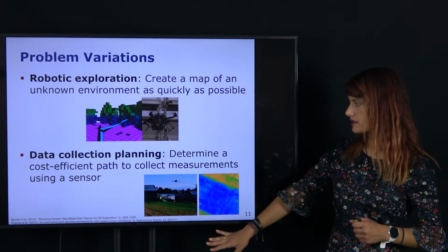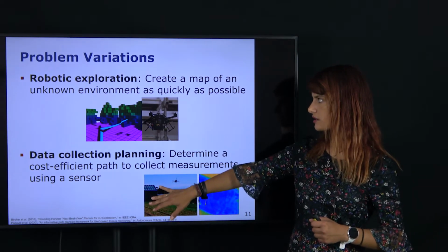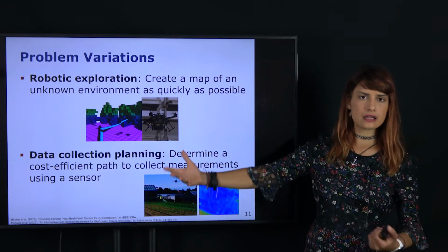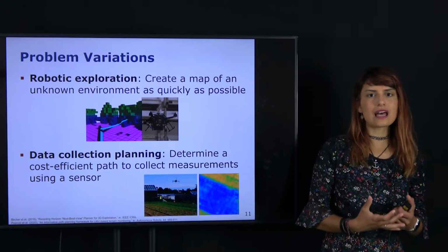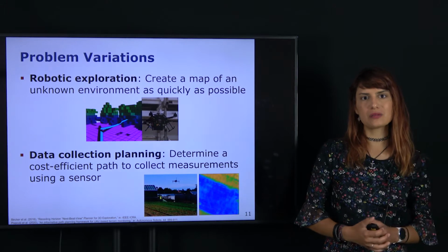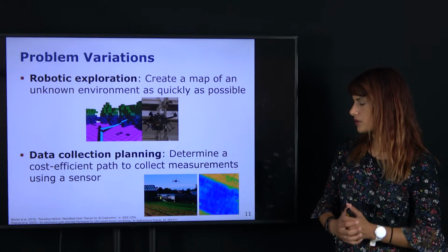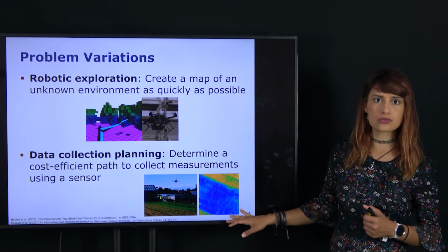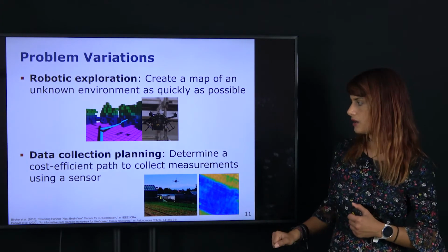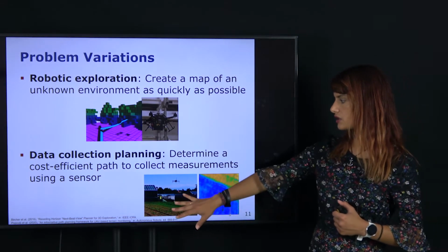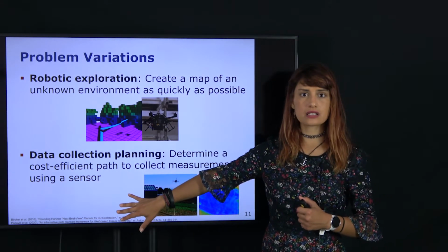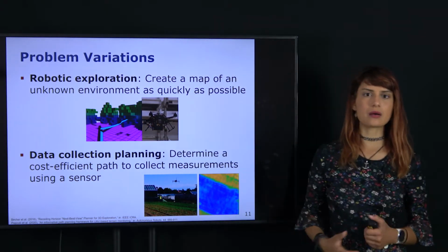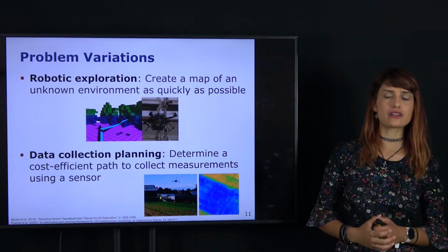In a sense, robotic exploration is simply a way of casting the data collection problem, because we're still gathering data and collecting information about occupancy, but we want to draw the distinction here because the map representations that we often use, as we will see, are rather different because of the differing nature of the target variables in environmental monitoring and in creating an occupancy map representing the structure of the environment itself.